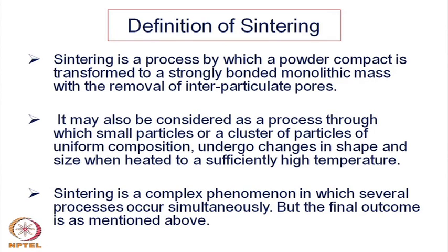So, one way of looking at sintering is basically removing the interparticulate pores and making a strongly bonded material. They no longer remain powders, but the powders coalesce with each other and make some strong chemical bond, and that is how the process of sintering can be described.